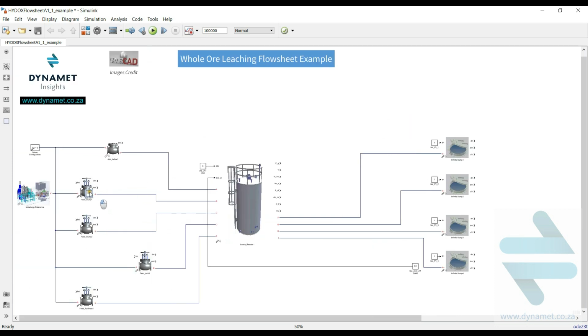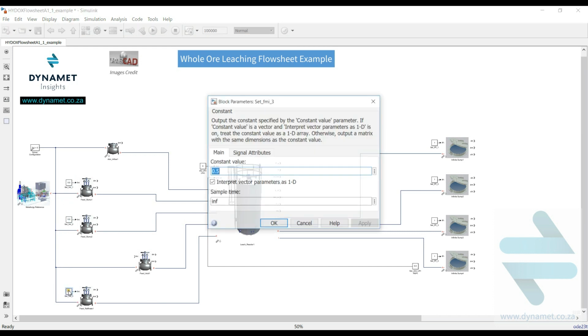Next, let's quickly set the inflow fractions. Let's make each of the two slurry feeds 50%. In other words, the total flow rate is correct and split equally between these feeds. The raffinate recycle stream is what it is, so we set this fraction equal to 1.